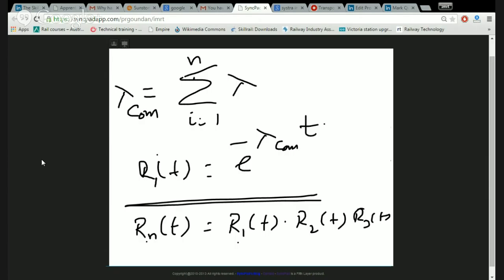Once you start, the cycle I told you day before yesterday in class: start with something, design, see whether it meets the requirement assigned, apportioned to each of these. If it doesn't meet, go and look into the components, look for a better component, a better pi factor, which has got a better reliability, then change the component. Like this, you have to do an iteration process, keep on doing it till you get it. And if you don't get it, then you go for standby, redundancy, things like that.